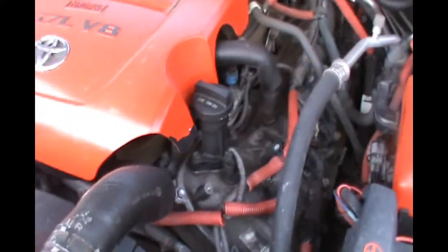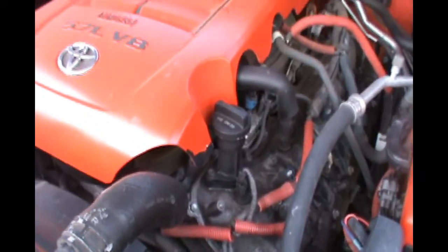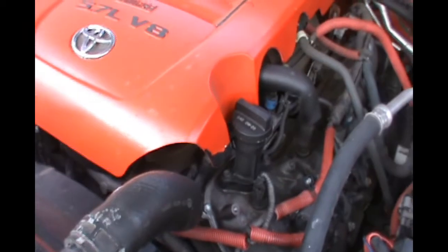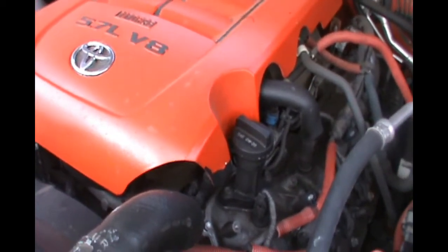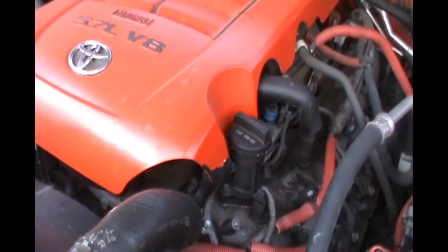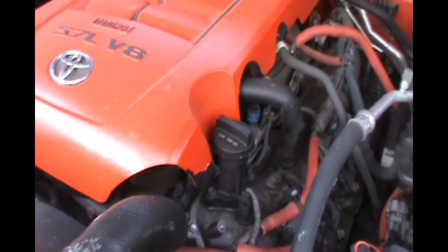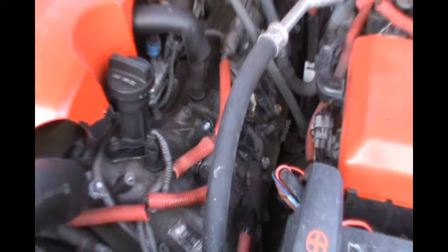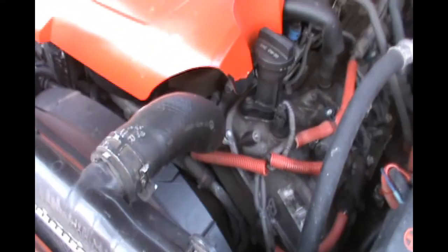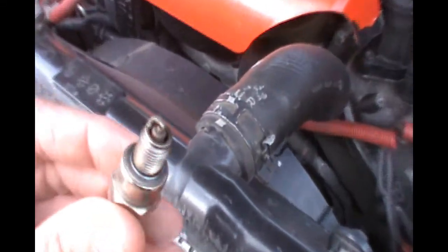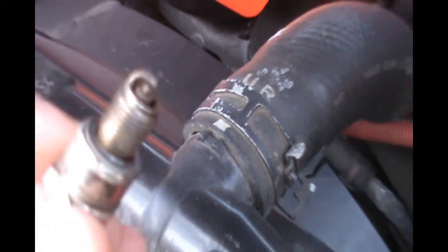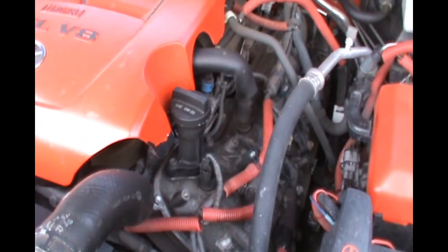A lot of vehicles, especially in the United States, call for an 87 octane, 85 to 87 octane rating. If you're running super or plus, which is 91 to 93 or even higher, it may not be the proper octane rating for the vehicle, and it may be running at the wrong heat range in the cylinder. And your spark plugs will show it. They can run lean, they can run rich, and you can get different colored tips. So, I know that this engine is between 30 and 35 thousandths of an inch.